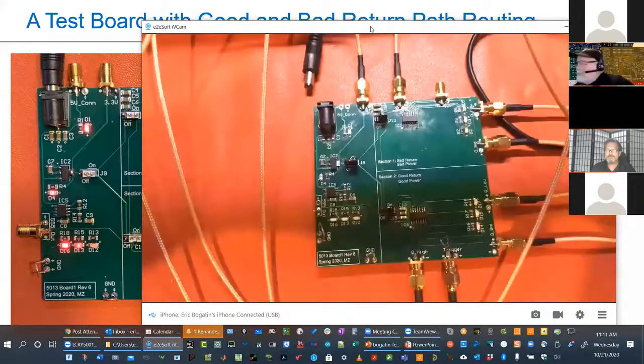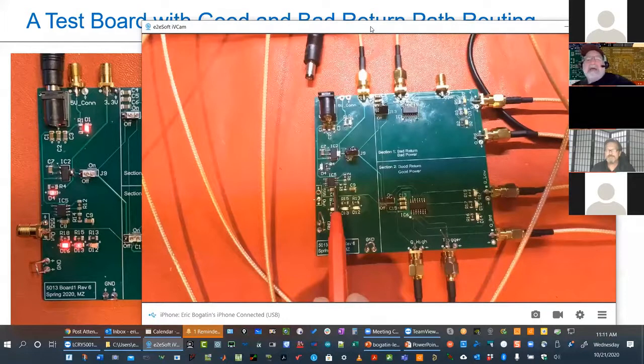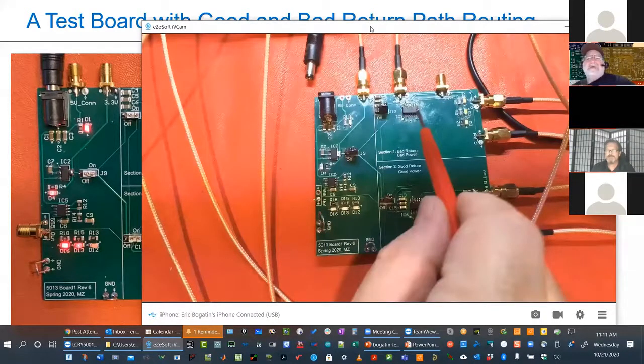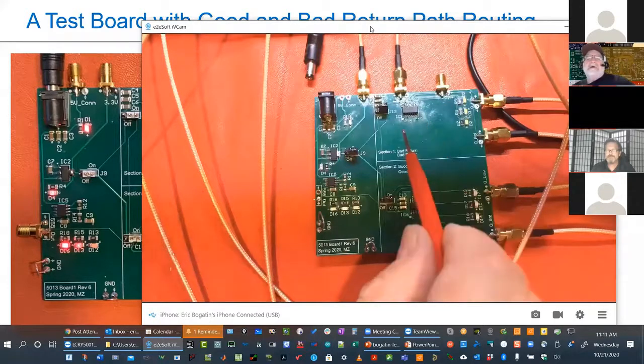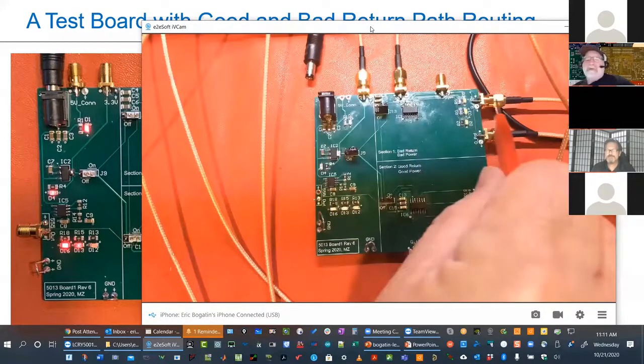We've got a little oscillator over here. It's a clock. It's going to drive a couple of hex inverters, and because a hex means 6 outputs, I've arranged one of them as a quiet high, one as a quiet low, one as a trigger, and the other 3 are going to drive some currents on these LEDs that we have over here.